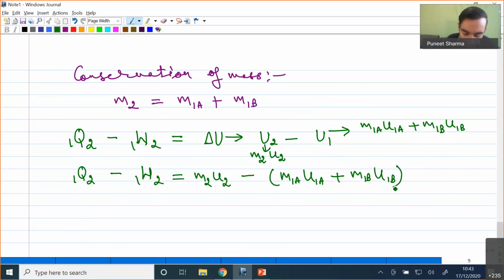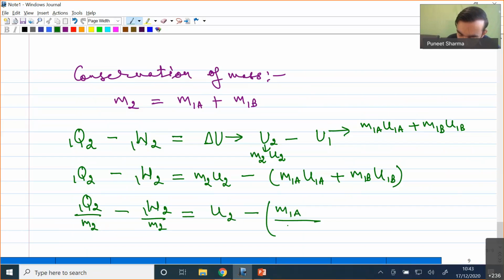Okay. So now if I divide throughout by M2, I'll be finding Q1-2 by M2 minus W1-2 by M2 will be equal to u2 minus M1A by M2 into u1A plus M1B by M2 into u1B. Okay. So this term over here is nothing but M2. Okay, my overall equation includes the work as well as the heat transfer.